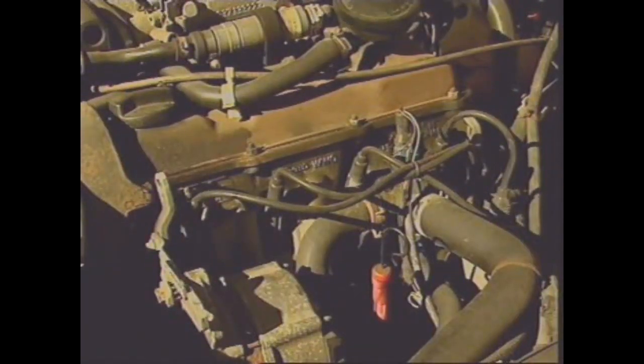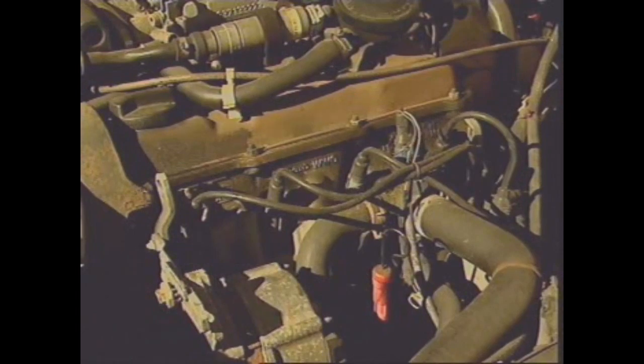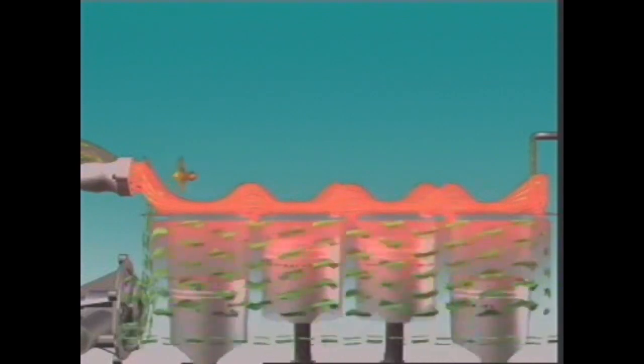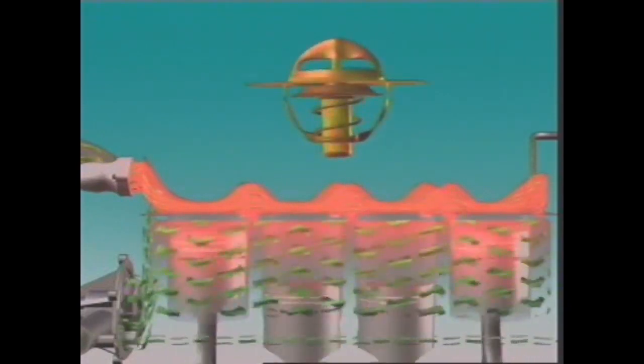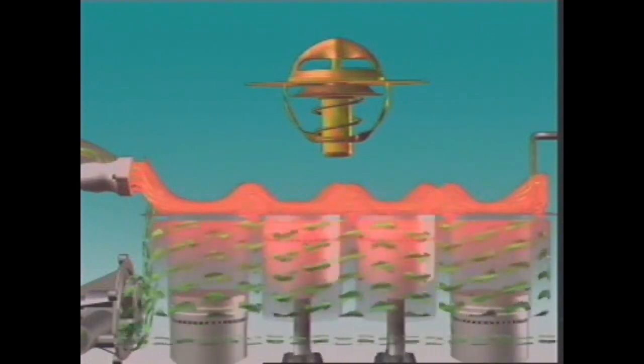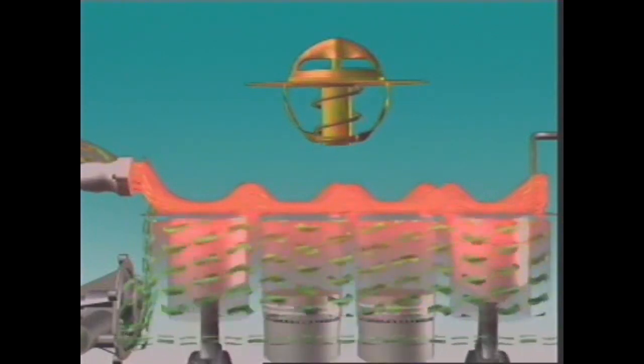Most engine wear occurs during this warm-up period, and most pollution too. One function of the thermostat is to shorten the warming up period. It operates according to coolant temperature. When coolant is cold, it is closed.